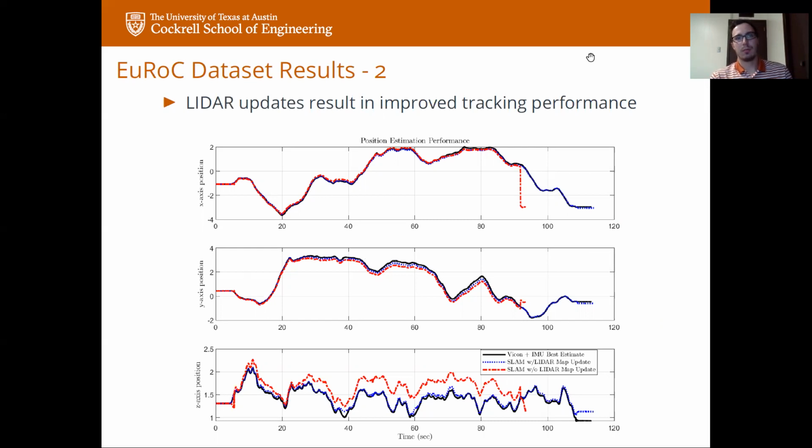We even have better robustness. Without LiDAR, the system loses tracking at about 90 seconds due to fast UAV motion. With LiDAR, the system has no problem tracking through this segment of the flight. Tracking is momentarily lost with LiDAR at the end of the flight. This is due to a large portion of the camera's field of view being obscured by the landing surface as the UAV lands.